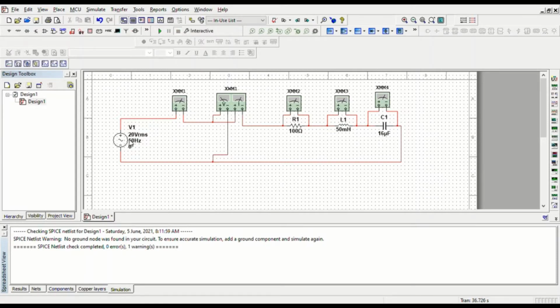I will change the voltage source to 30 volt. The current here we get 144.132 milliampere. The power here we get 2.077 watt. The voltage here we get 14.413 volt. The voltage here we get 2.271 volt. And the voltage here we get 28.582 volt. The voltage source we will run until 100 volt.